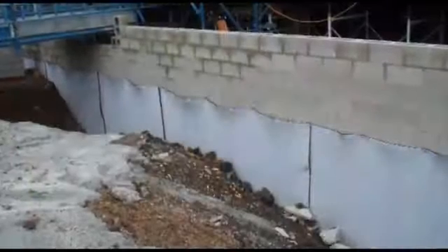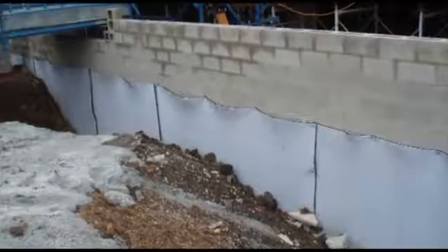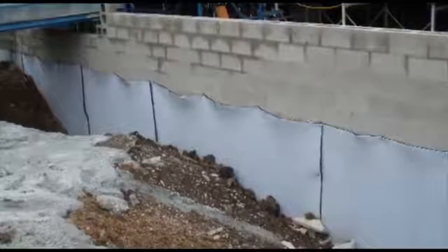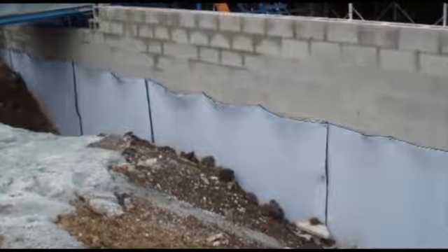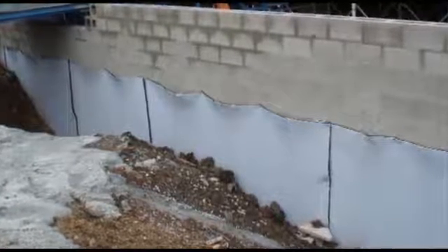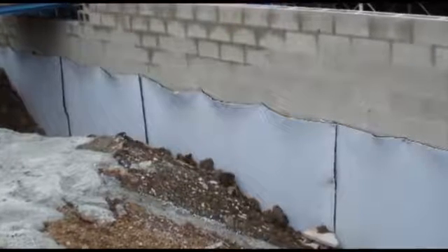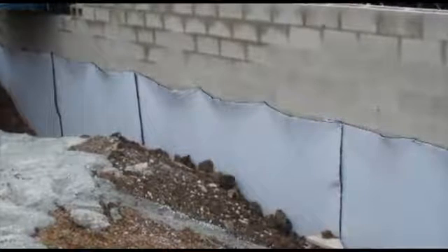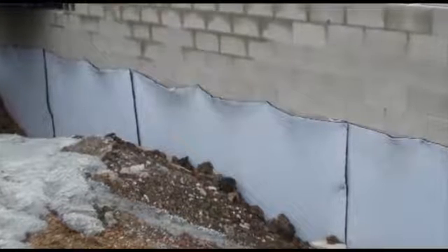Here we see a geosynthetic sheet drain being placed behind a bridge abutment to move the water down and away from the structure. By minimizing the water behind the abutment, the engineer can lessen the imposed load by reducing the pore water pressure acting on the wall. It also means that there is no water leaking through the wall and staining the visible face of the abutment.